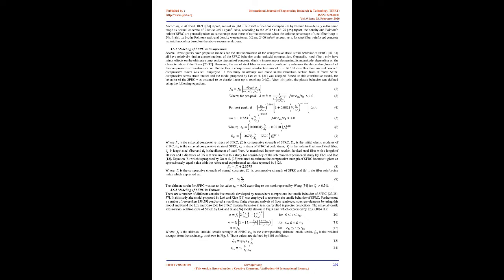3.2 Interactions between components. The embedded approach was adopted for the interaction between the SFRC and the steel reinforcement, which enforces displacement continuity and the perfect bond between the two elements. The interaction between concrete and reinforcement after cracking was incorporated only in a simplified way using the tension stiffening in the concrete model. This was adopted to approximately simulate load transfer between cracks over the rebar 18,19. The interactions between the surfaces of the inelastic and elastic solid bodies representing the concrete material and the loading steel plate is modeled using tie constraints.